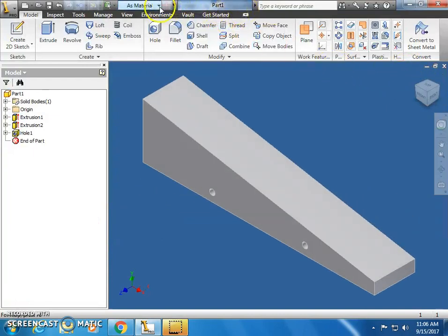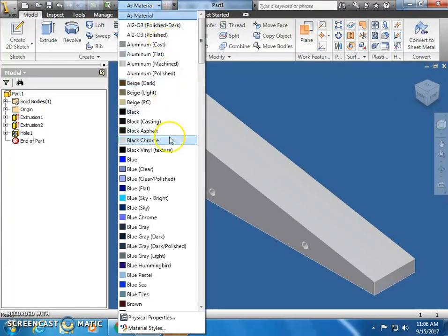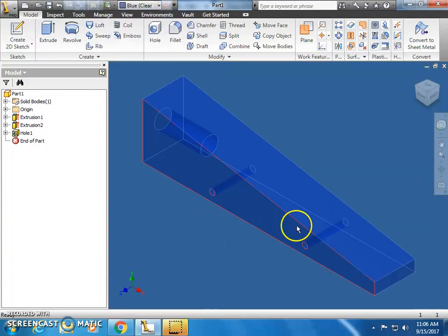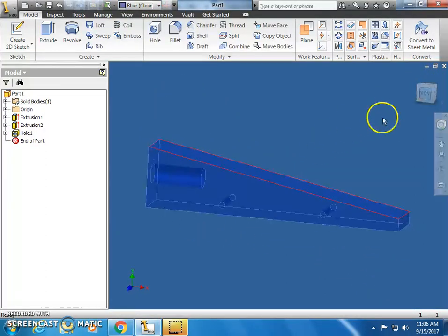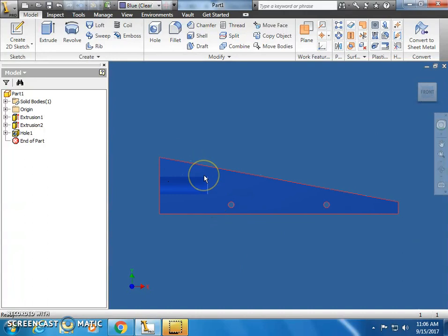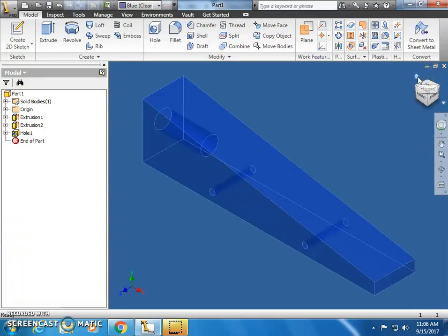Please change the material to a clear material. This will help you later in designing your dragster. You're not going to want to cut into the CO2 hole. You're not going to want to have an area that's too thin, so your dragster snaps.